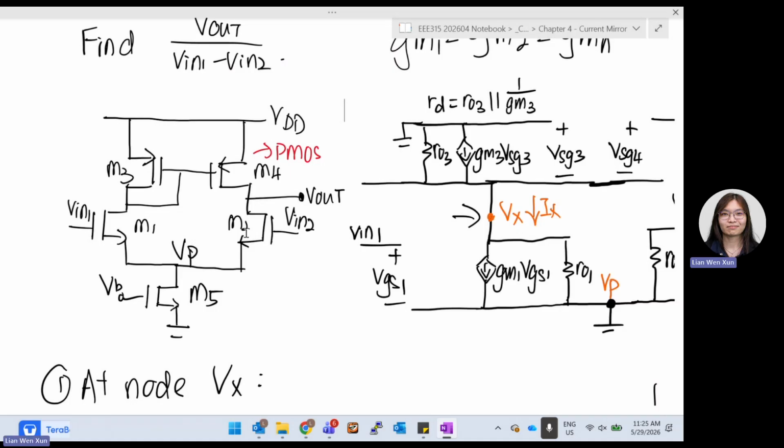So we know that for PMOS, it is one line on top, two lines below. So we draw one line on top, two lines below. For the first one first, we go part by part. Usually in this case, we will see what happens at the source and what happens at the drain. Sorry, I left one off. I connected here. So we go part by part and check how we draw this.